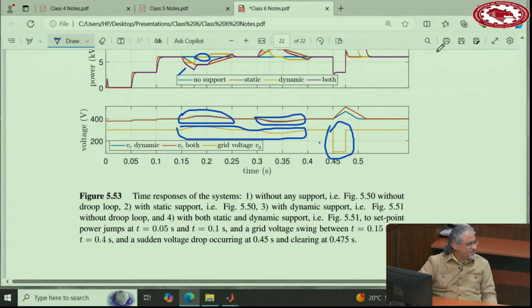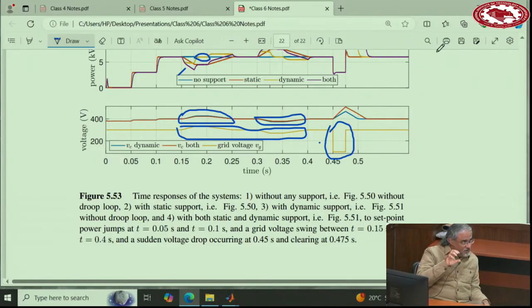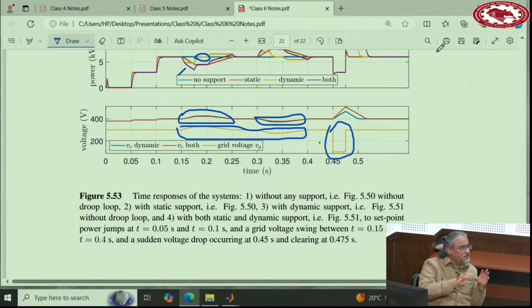Will these terms, this R1, J, impact the stability of the overall system? And how do we design these? In the full state feedback design, no, because we consider them in the design. Now if you designed partially the current controller and now start playing with R1 and J arbitrarily, yeah, you may destabilize the system. But if you choose them first, R1 and J, then go and design the entire system, full state feedback, you are guaranteed that it's stable.